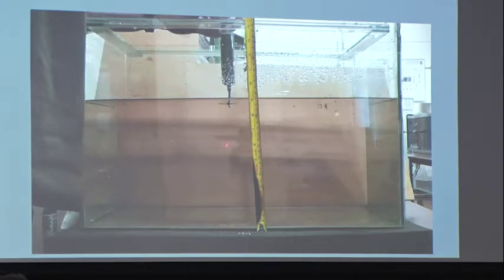I'm going to let the plume entrain water. And what lands in here is going to be the smoke, no? So MS will be the volume of the smoke. MF will be the fuel that I'm injecting. Is that okay? And the difference between the two of them is the air entrained. In this case, the water entrained. Is that clear? Why am I doing this? Because I want to get a sense of which one is bigger.